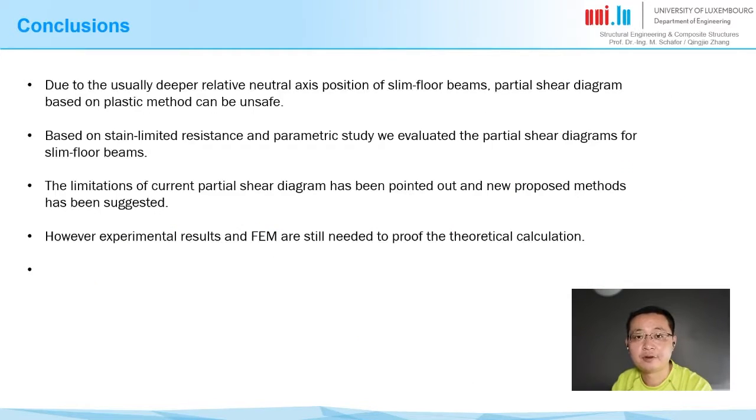So here I will make a conclusion. Due to the usually deeper relative neutral axis position of slim floor beams, partial shear diagrams based on the plastic method can be unsafe. Thus, based on the strain limit resistance and a parametric study, we evaluated the partial shear diagrams for slim floor beams. Based on that, we give the limitations of the current partial shear diagrams and also give a new proposed method and its usage.